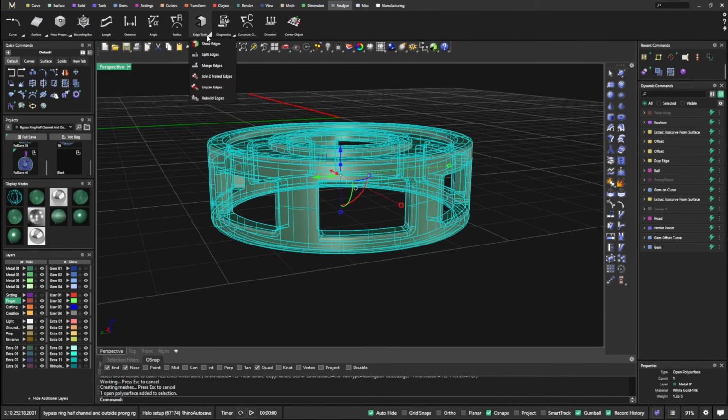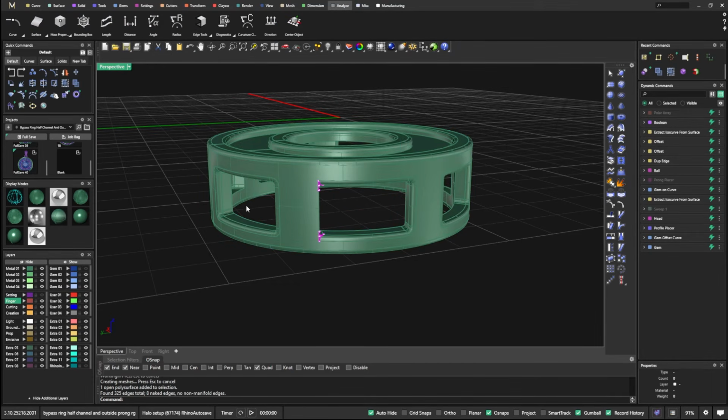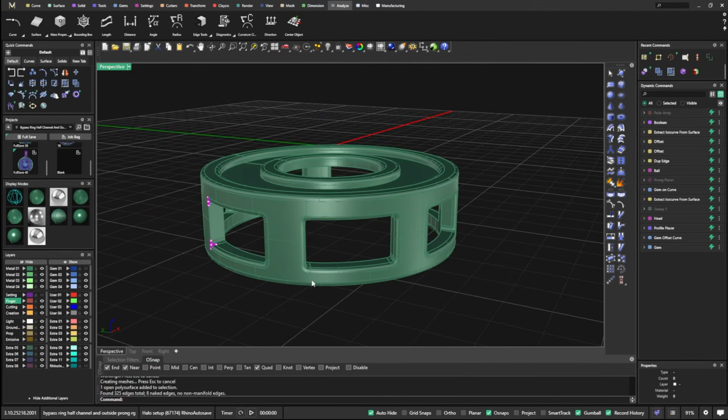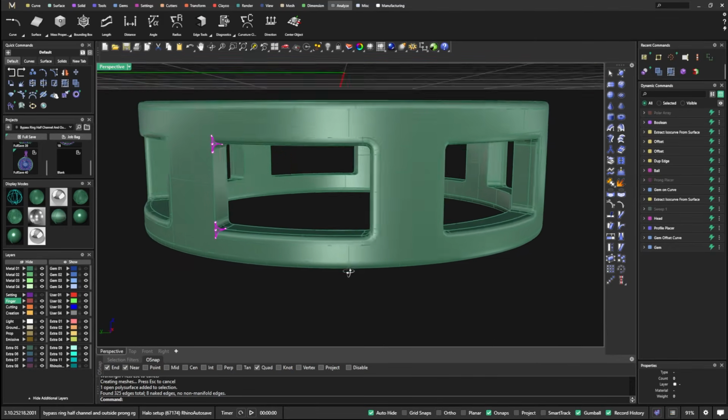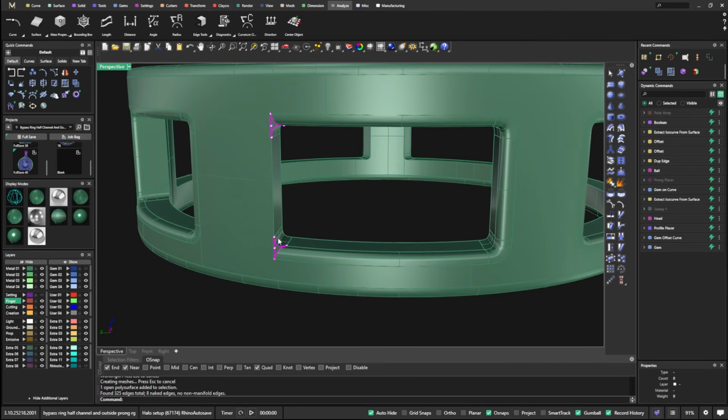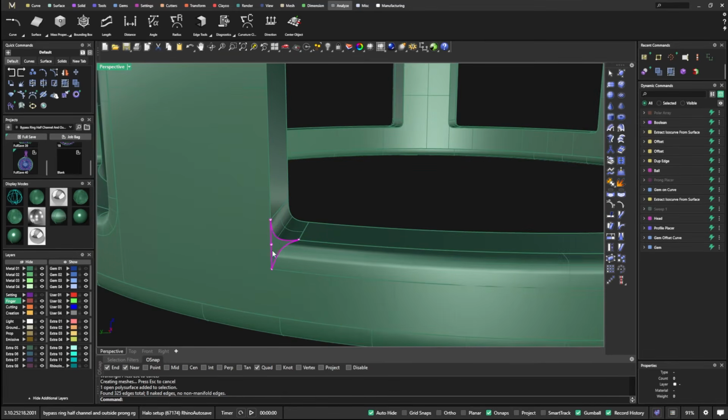Analyze, right? Edit meshes, show edges, right? And I have my tool over here, show naked edges, right? So it's saying that we have 8 total naked edges there. The rest of them came out good. These right here did not. Major bummer. So there's a couple ways we could fix this, but since it looks like there's 1, 2, 3, 8. 1, 2, 3. So there's 4 there.